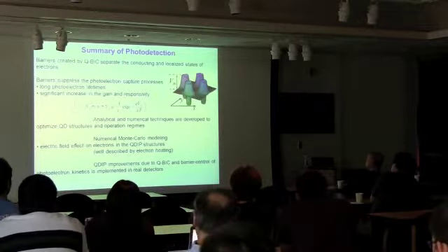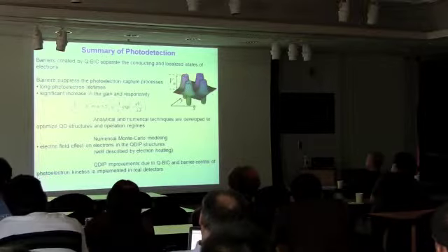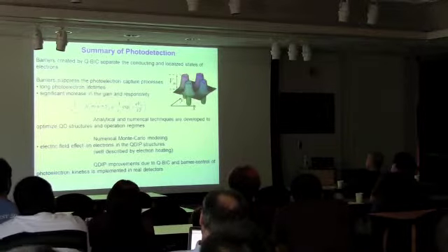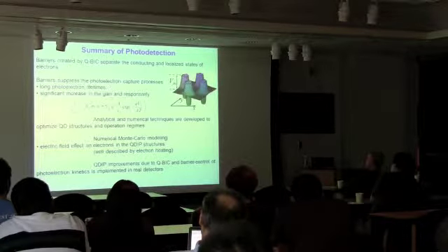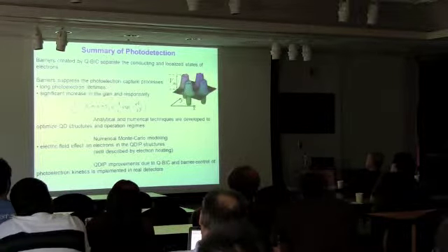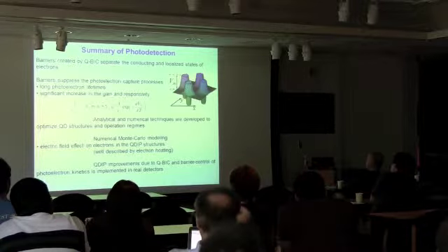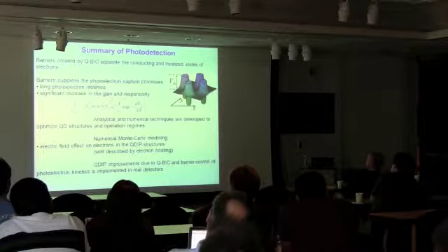It means that if you throw one electron out of the dot, it can go through the circuit 1000 times before it will be captured, because it goes to the minimum of the potential profile and does not want to go back in the dot.